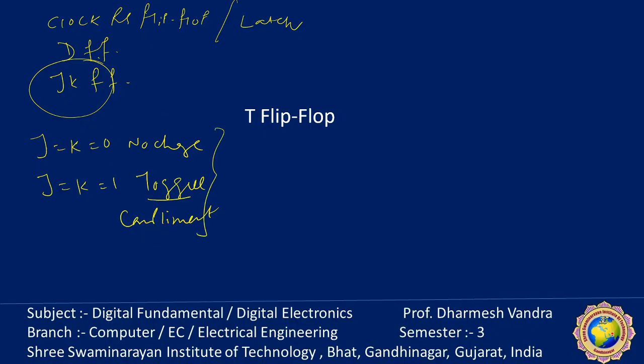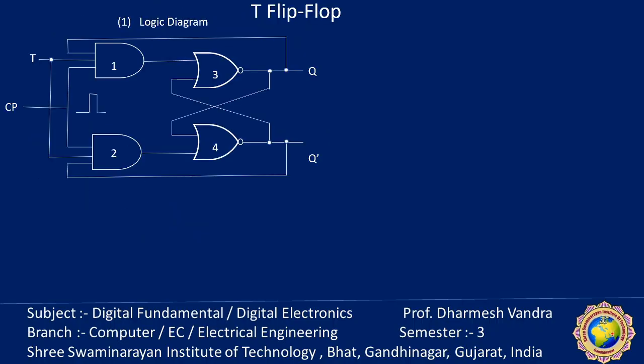So the T flip-flop is a single input version of the JK flip-flop as shown in this figure. Here J is directly connected to K, so J equal to K equal to one input, which is called the T input. So only two conditions occur. The circuit is similar to a JK flip-flop, and here both the inputs are tied together. The T comes from the ability of the flip-flop to toggle or change state. So remember that, the circuit truth table is like this.